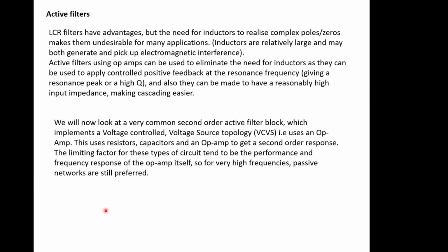Right, so that was a passive filter, second order. It's what's called an LCR filter. They do have some advantages, but they have to have inductors to realise complex poles and zeros. We haven't talked about zeros yet, we will do.